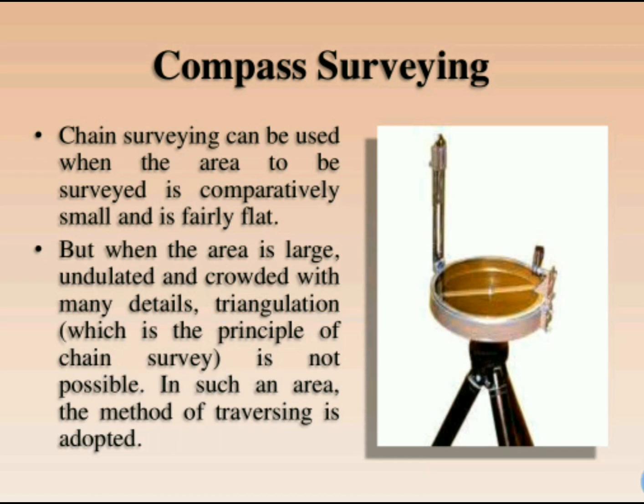Yes or no? Why? What is the principle of chain surveying? Triangulation. So if triangulation is not possible, then we cannot use chain surveying. So here, to overcome all these problems, we want to use the traversing method.